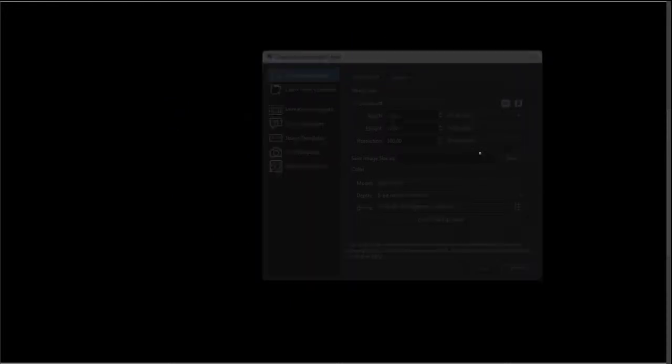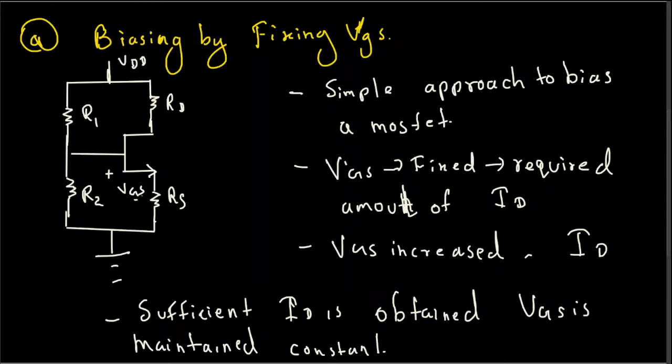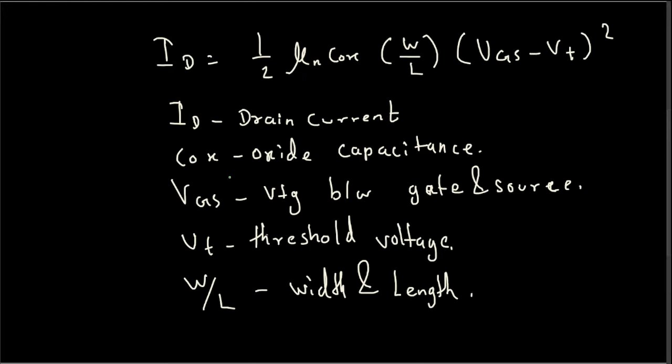And we can use the same method for two MOSFETs as well. We can use two MOSFETs to do the same type of biasing, but it's not very common. But the thing is, when we do that, that's going to change the ID, because if you choose two MOSFETs, the parameters are going to be different. In ID, this width to length ratio may differ, and that V threshold may differ, VGS may differ. So the current value is going to be different for two different MOSFETs.